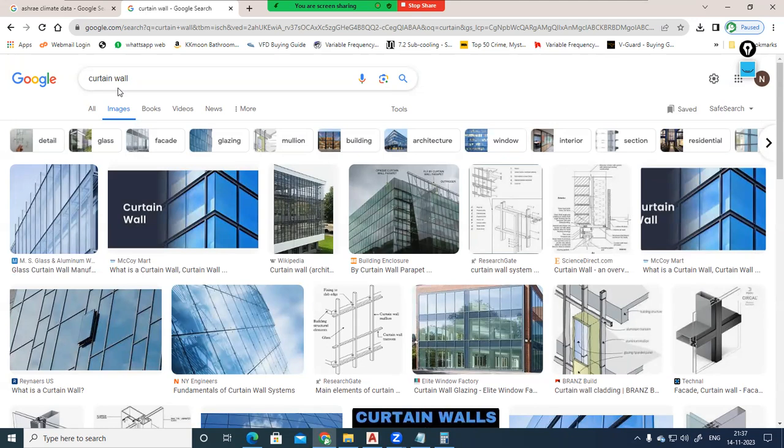Even if we are proposing these inert gases, visible light rays are entering inside. If you are proposing inert gases like argon and krypton, that will act like a thermal insulation material. It will prevent conduction heat transfer up to a certain extent. But radiation heat transfer is not possible to prevent by normal thermal insulation material. The visible rays entering inside are electromagnetic radiation only. Radiation heat transfer should be considered.